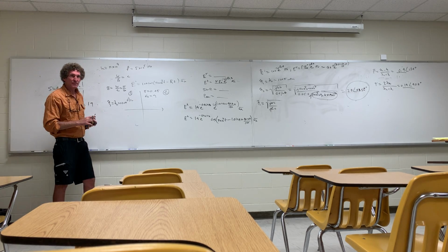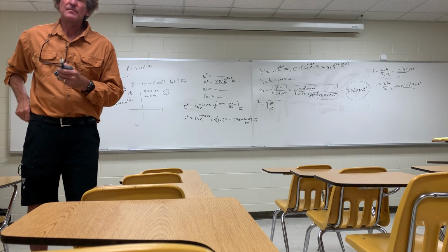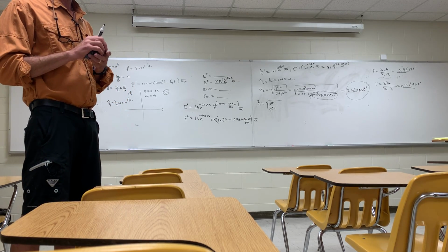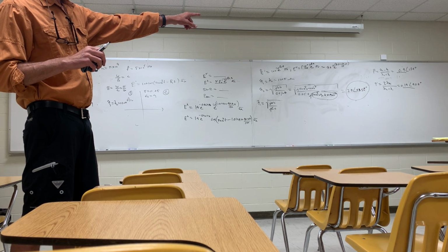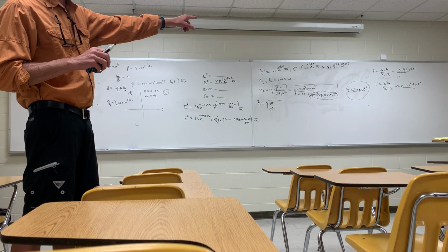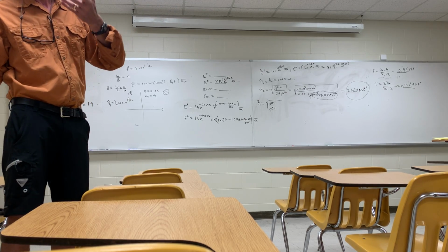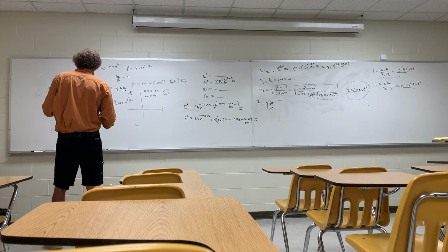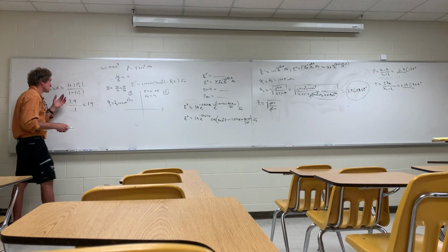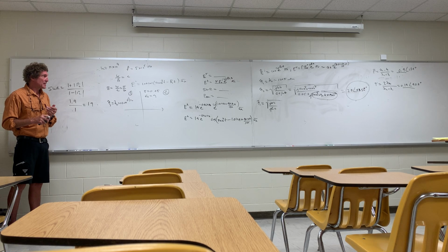Does he have a standing wave ratio of 19 for that one? Sure. 18.6, so yeah, 19. So that isn't 0.9 exactly then. See that reflection coefficient? It's probably 0.8, so that's where the error is. But fundamentally, that's how you would get it. Just find the reflection coefficient. 1 plus the reflection coefficient over 1 minus the reflection coefficient is the standing wave ratio of the electromagnetic field in the air.